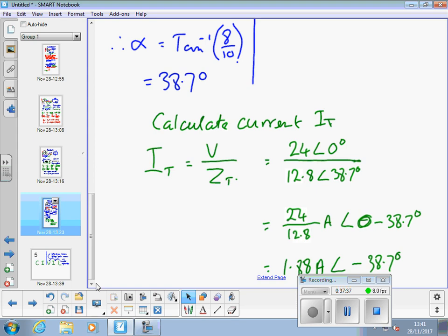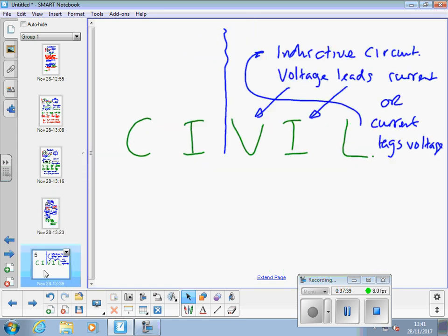Have to be a little bit careful with that when we've got both capacitors and inductors in the circuit, because that angle will be telling us whether the circuit as a whole is capacitive, i.e. there's more capacitive reactance in it than inductive, or vice versa. But when we've only got one type, that's a definitive check. Okay? So, are you all happy with that?